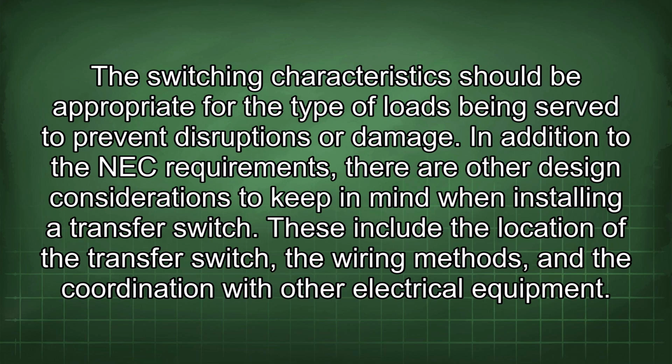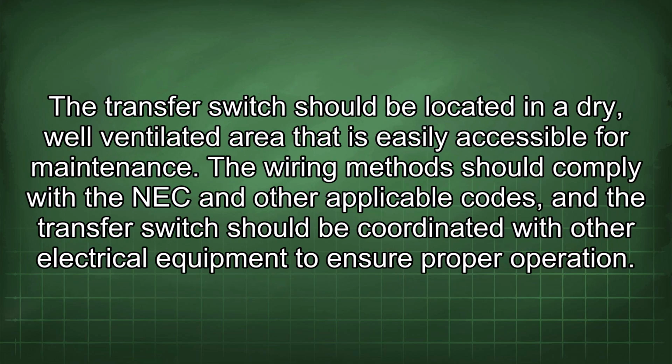In addition to the NEC requirements, there are other design considerations to keep in mind when installing a transfer switch. These include the location of the transfer switch, the wiring methods, and the coordination with other electrical equipment. The transfer switch should be located in a dry, well-ventilated area that is easily accessible for maintenance. The wiring method should comply with the NEC and other applicable codes, and the transfer switch should be coordinated with other electrical equipment to ensure proper operation.